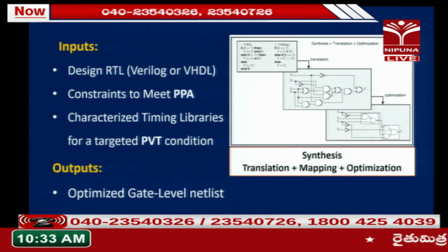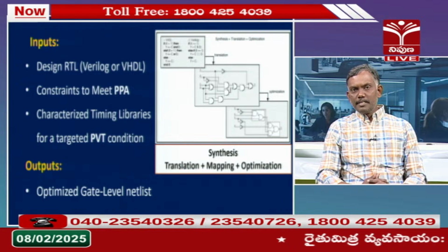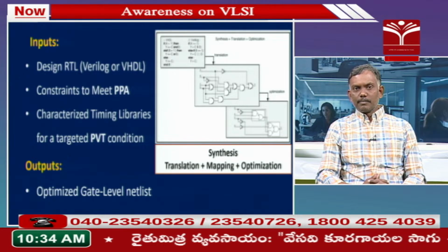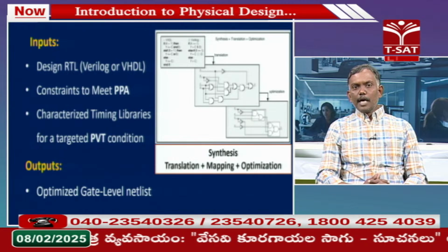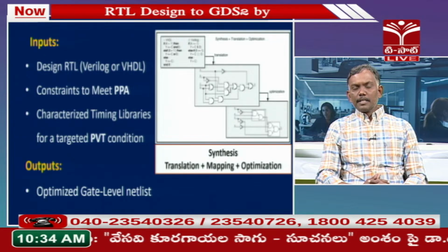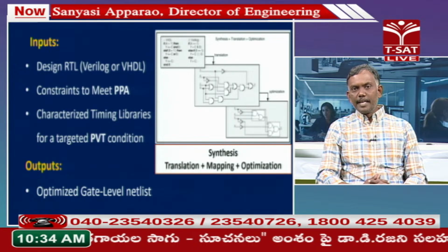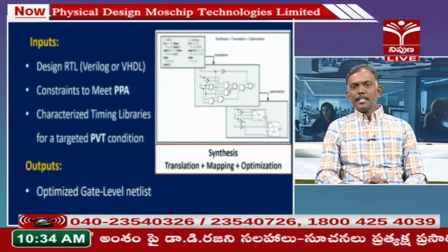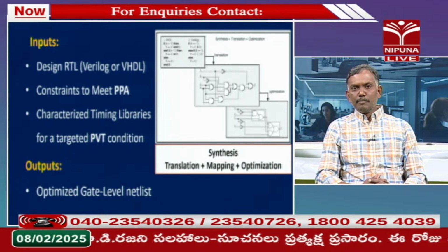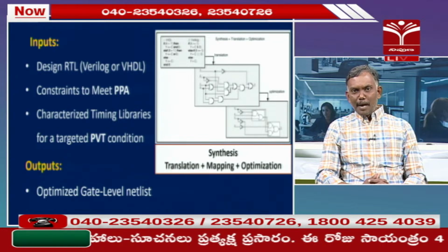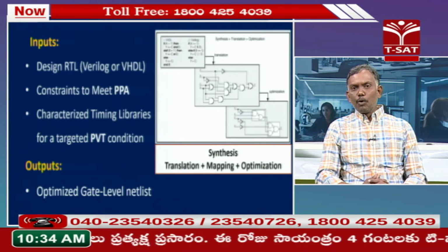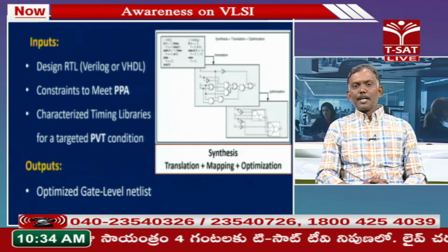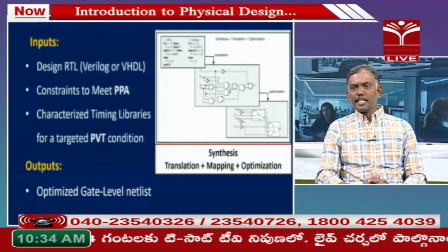What is this performance check? Performance check means how fast the signal is coming from the input to the output. For example, take B to Y. I am applying a signal at the B input. The change in signal at input B, after what time are you seeing the response at the output? That is what we can call the performance check, meaning how fast it can come. After mapping all the gates, let us say one of the possible combinations for B to Y is an AND gate followed by an OR gate, an AND gate and an OR gate. 4 gates are present in that path.